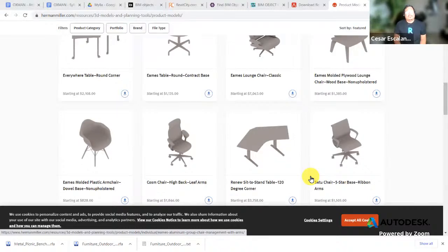But don't copy this family across everything. What I tell my users sometimes is you have your documentation model, which is used for construction documentation, and then create a new project. In this project, link the documentation files, and then use this file as a rendering model. In this rendering model, you place all these pieces of furniture that are really big in size, but you don't contaminate your documentation model, which continues being lean and manageable.